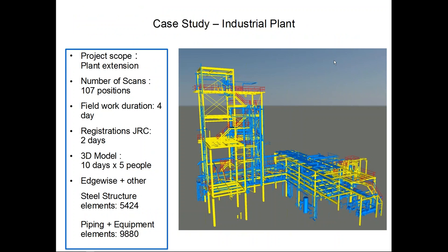So let's say for that project that I showed you before, 107 scan positions, we have managed to register it successfully within 2 days. And that's a very good time if you consider this against any software that does it by identifying targets. I think if we would have had to make this project with targets, it would have taken one person from our team at least 3 days to identify the targets in the point clouds, and then again like 2 days to arrive at the point where we can actually export our ready to use point clouds.